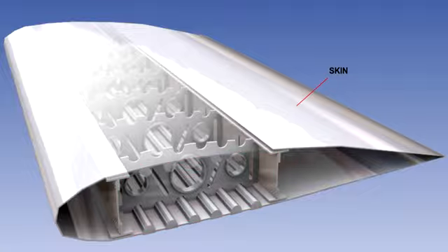The stressed skin takes the loads due to the differences in air pressure and the mass and inertia of the fuel in the wing tanks. It generates direct stresses in a span-wise direction as a response to bending moments, and it also reacts against twisting forces.